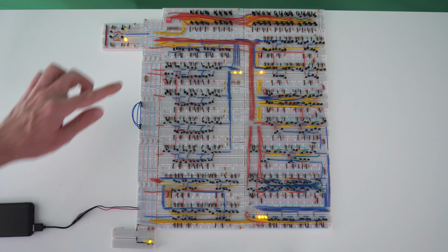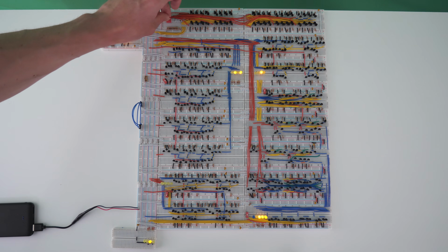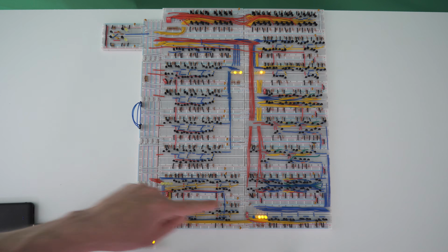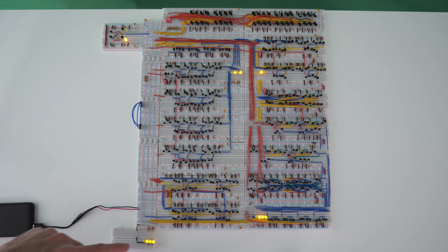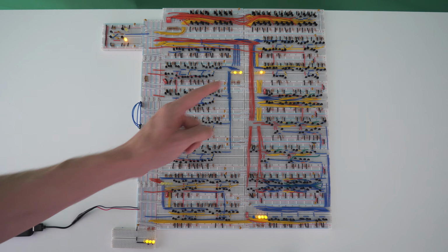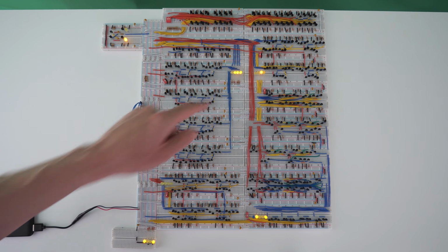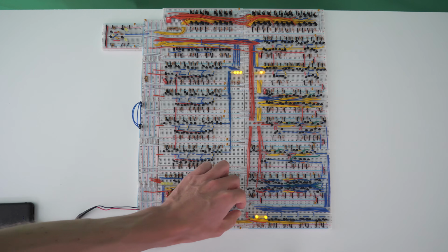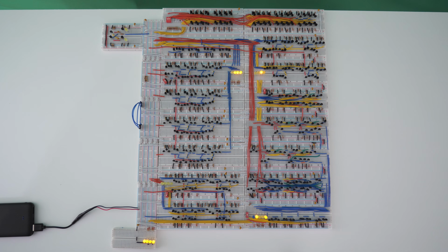data bus, but we actually forgot to make it so that our memory is no longer connected to the data bus. So we have to flip this switch first, and then we'll make it so that the ALU is connected to the data bus by flipping this switch here. And now we have a value of 7 on the data bus, which we're going to load into register A by flipping this very quickly. And now we have a 7 in our A register. So we will make it so that this is no longer connected to the data bus. And now all of our add commands are complete.